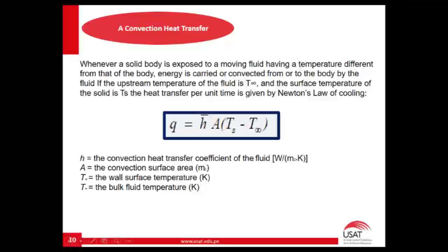The heat transfer per unit time is given by Newton's law of cooling. In this case, h is the convection heat transfer coefficient of the fluid, A the convection surface area, Ts the wall surface temperature, and T infinity the bulk fluid temperature, in Kelvin.